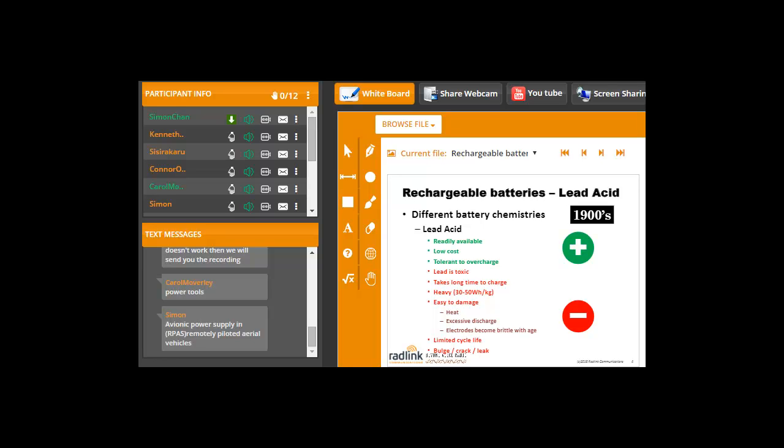Now, for those of you who've been involved in power electronics, you will know that a lot of our components, MOSFETs, transistors, etc., can reach 150 degrees C just in normal operating conditions. And of course, in an overcurrent condition, this will really be catastrophic. This particular battery will catch fire and go up in flames and leave a bit of a mess. And cobalt is not a friendly chemical, so it can leave toxicity issues.